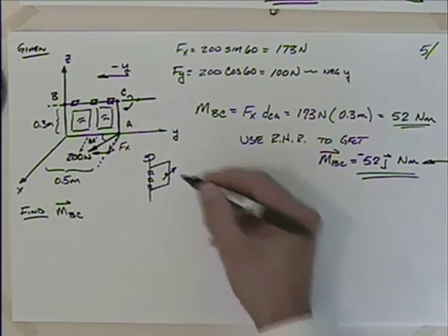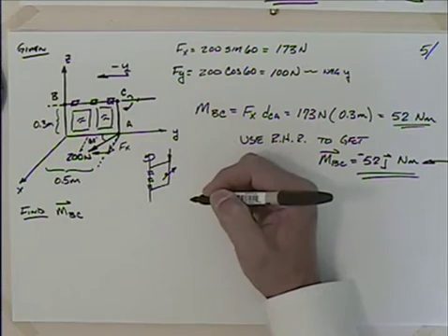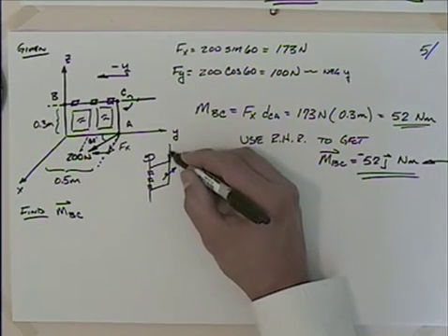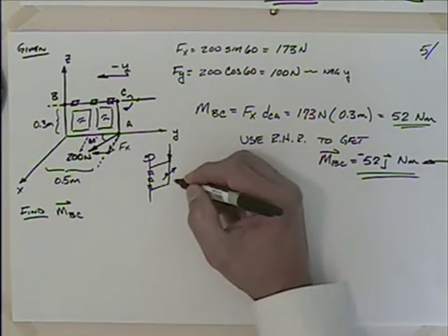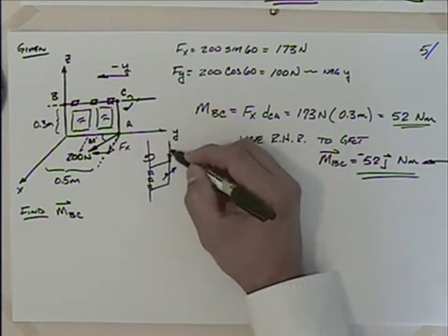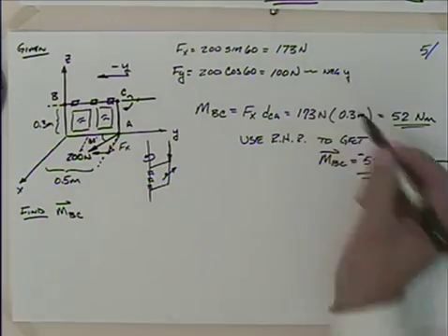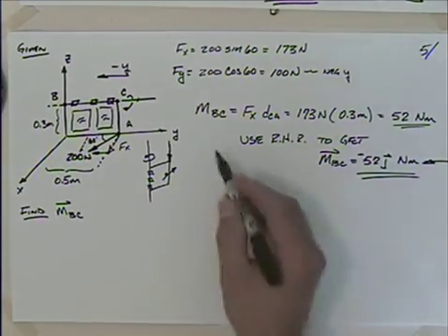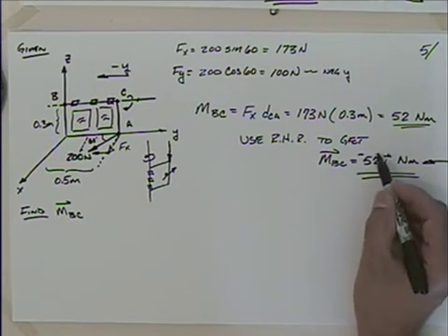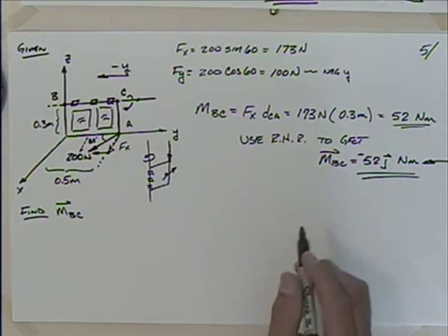Whereas if you hang your coat on the corner of the door, okay, or you hang on the door or something like that. If you apply this force there, does that open or close the door? Certainly it does not. So it's parallel with this axis and causes no moment around that axis. So that's why we got to ignore the y piece here. Well, if our right-hand rule and whatnot didn't make a lot of sense, let's try this with a vector approach.